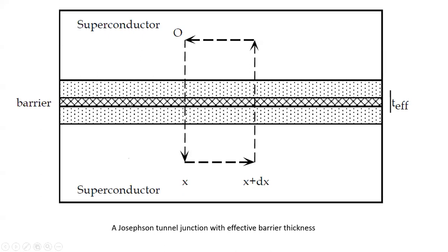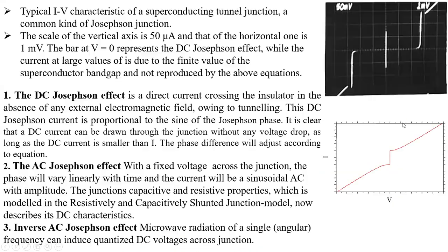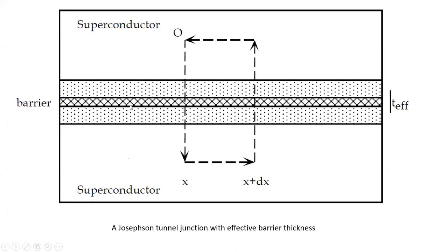These are superconductor 1 and 2. Here, what I am showing is the same case, superconductor 1 and 2. This is a barrier. This is an enlarged image only for you to understand. What happens if you are interested in choosing only between the two regions, X with some delta X, the barrier? The barrier thickness will reduce, and the tunneling process can happen.